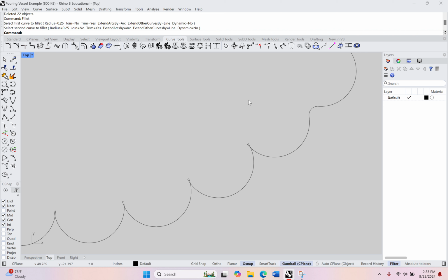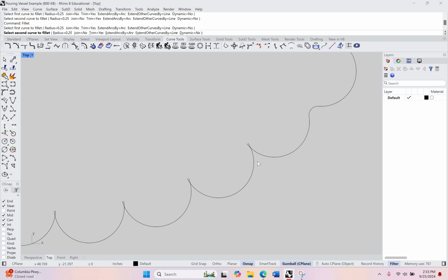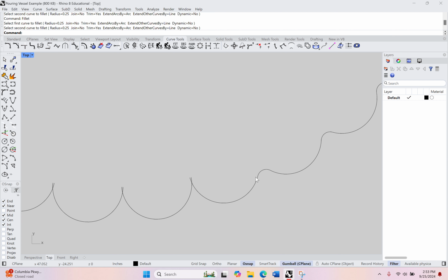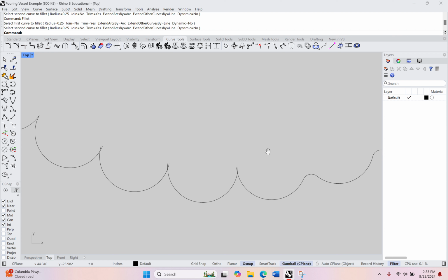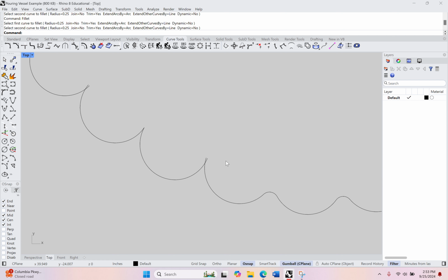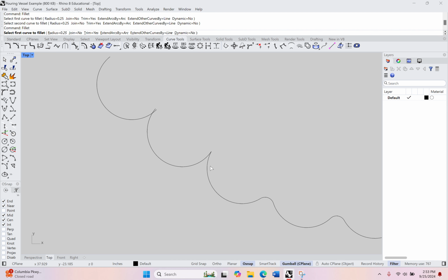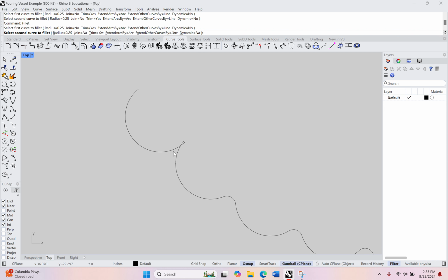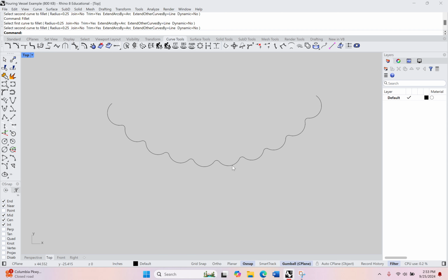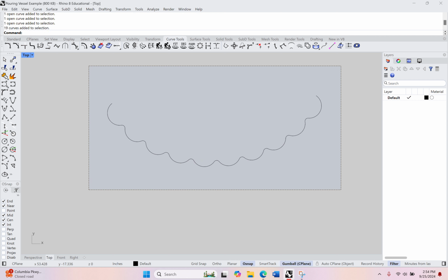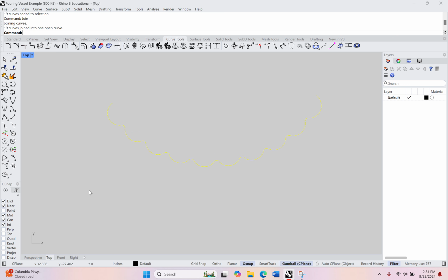So right click or control click if you're on Mac to re-equip the previously used tool. And if you're happy with the dimensions, you don't have to make any changes. You can just right click and then click, click, and just walk around this series of semicircles. Okay. Now, all of these are still separate curves. To make it simpler to use, I'm going to select everything, join in the command bar. That's a good habit to get into, is to join everything if you don't need them to be separate.